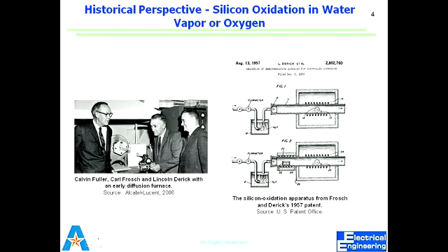If I need to make electrical connection, how would I approach silicon? Say I make an opening by etching, as was said. Now I need to approach the silicon. How do I do that? You can use photolithography, which I will do to define this pattern before I etch. Then deposition: we'll deposit metal which will go everywhere. Then I will do another lithography, make a design again on the surface, and remove metal from everywhere else. This will give me a contact with silicon. I've skipped many steps in between, but we'll see how.